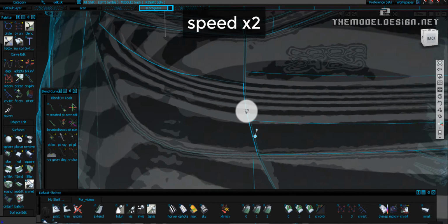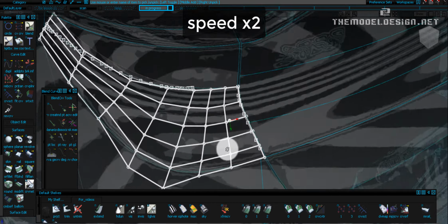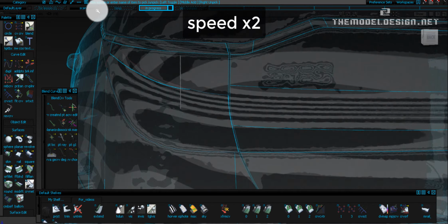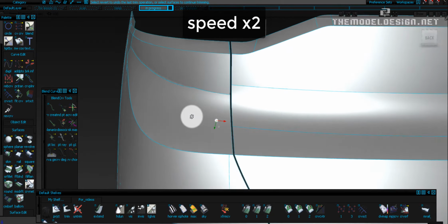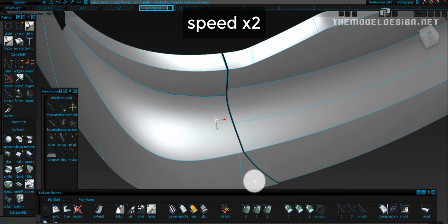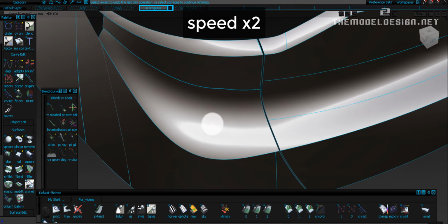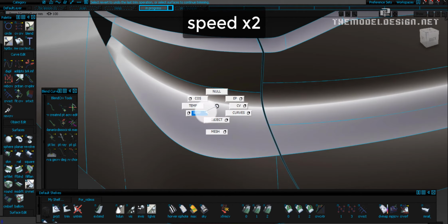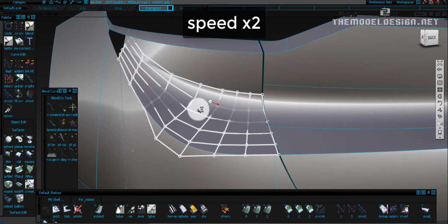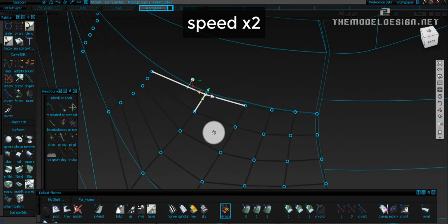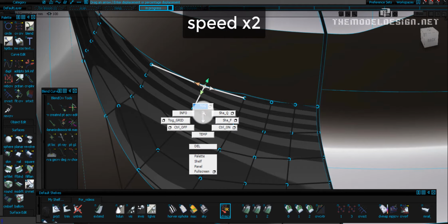At the moment, the highlight is good, the zebra stripe is not too bad. I did a lot of CV movement to optimize each of the CVs. I don't like CVs unnaturally dripping down or standing proud too much. I look from all possible angles to optimize them as soon as possible. There is still some room for improvement available. We can take this opportunity to slide the CVs a little bit more.